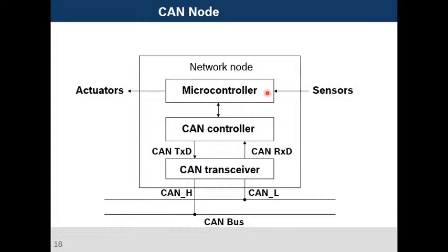Once the ADC value is received by the microcontroller, it is transmitted to the CAN controller. The CAN controller handles the CAN frame format, so the microcontroller gives only the data part. Once we go through the frame section, it will be clear.